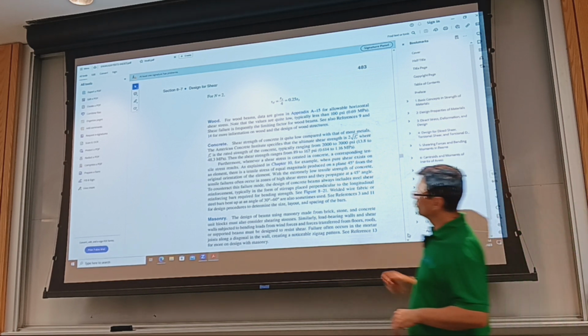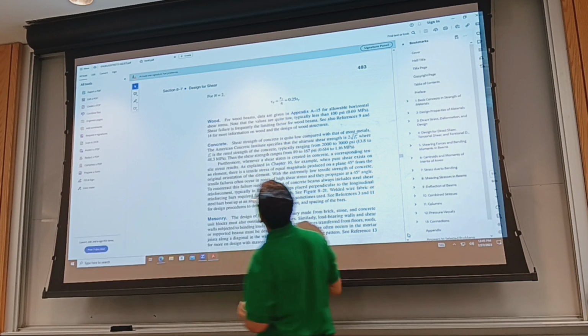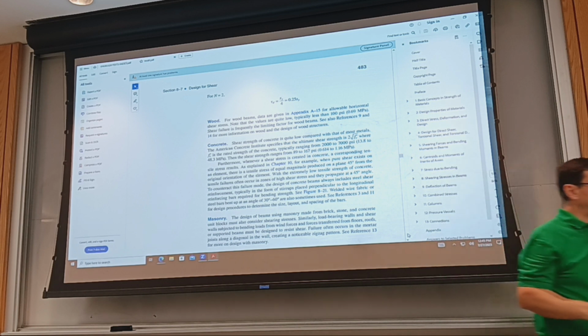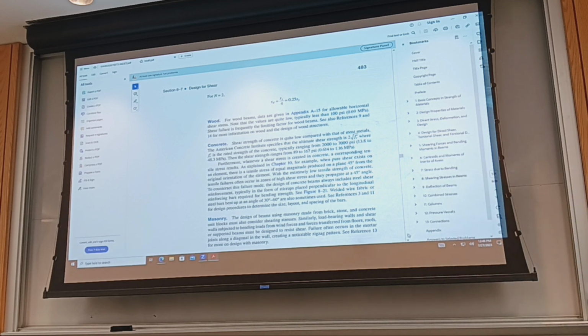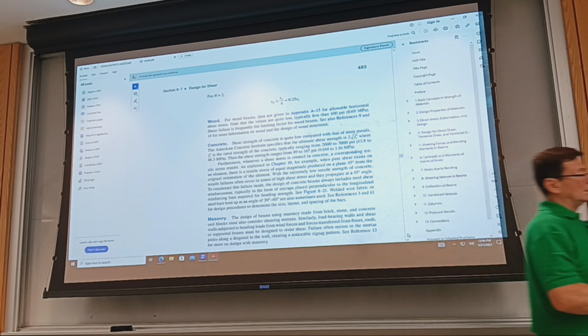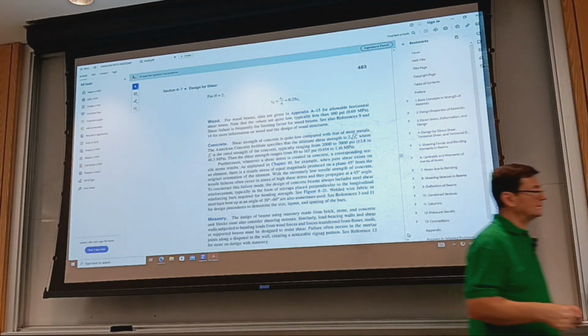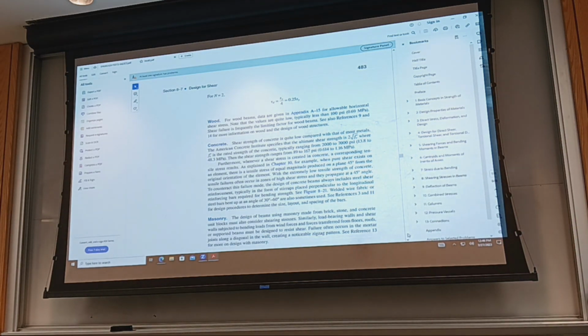For wood beams, for concrete, for masonry, they have recommendations. In catalogs of wood, based on the wood grade and species of wood, they give you directly what the maximum horizontal shear would be. Composites, being laminar and anisotropic, are likewise weak in shear, prone to delamination.